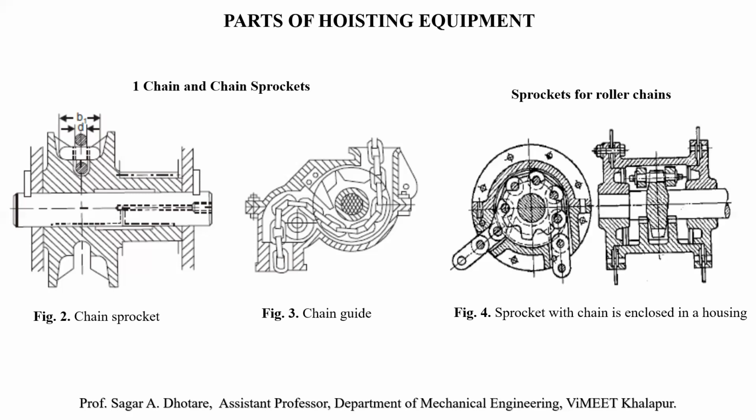Then there is heavy wear of links, low safe speed of movement, and sudden failure can occur without indication. Flexibility in all directions is very low, and the possibility of using small size pulley and drum is very low. Simple design and manufacturing process is an advantage. The diameter of the welded chain pulley drum is about 20 times the diameter of the rod of the link.